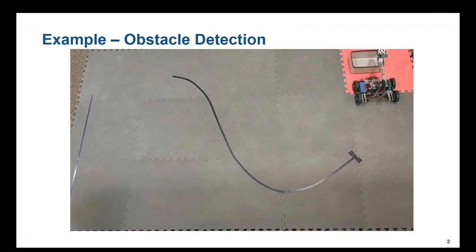For example, we may place the robot at this safe distance from the basket and lower the object in its arm. So the basket is our example obstacle. The robot is equipped with an ultrasonic sensor that will tell us how far the obstacle is away from the robot. Obstacle detection is a basic way to perform localization for robots. Localization is the ability of a robot to know where it is on the map.